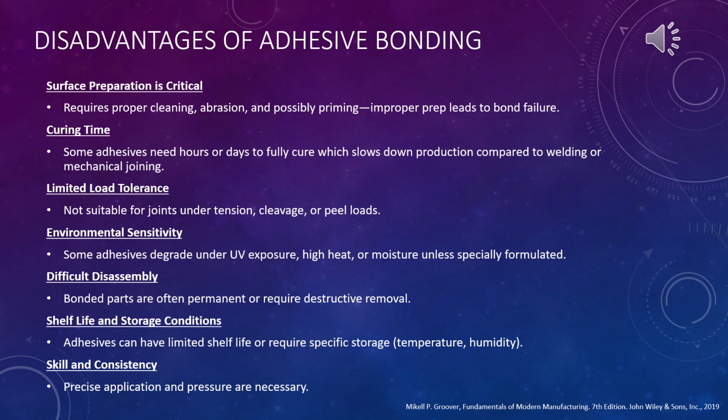Number 3 is limited load tolerance. It's not suitable for joints under tension, cleavage, or peel loads. Adhesive joints perform best under shear loading. This makes adhesives unsuitable for many structural or load-bearing applications without additional design considerations.